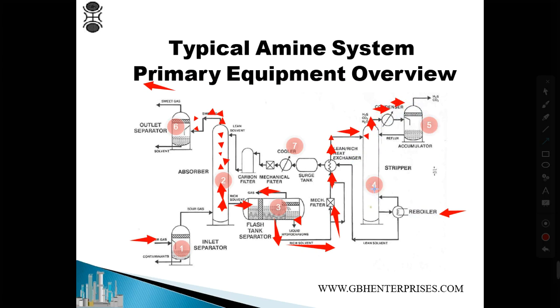And now since the H2S and CO2 are removed from the amine and go out to the accumulator, the clean and lean amine goes back to the system. So lean amine actually goes back to the system. And then of course we have a set of equipment here, just to clean and filter it, because maybe there is some impurity, some solids. Because we want a very clean amine, it goes through all this filtration and cooling process, and then the rich amine is sent to here. So this is the whole process.